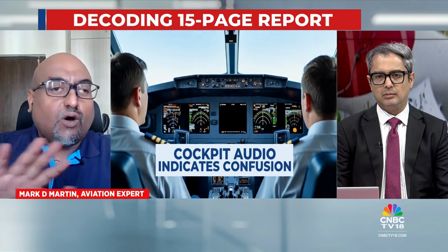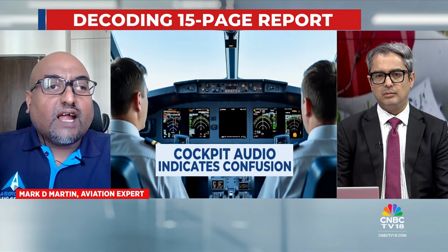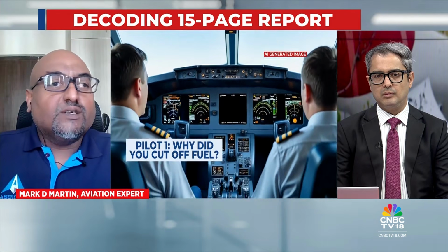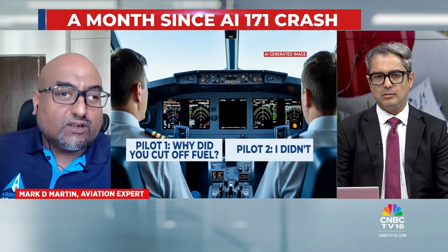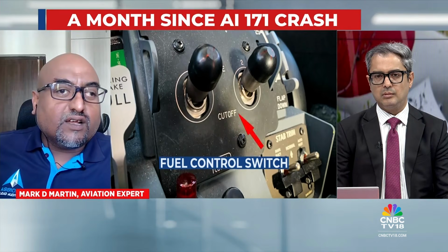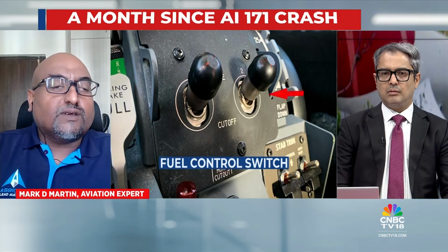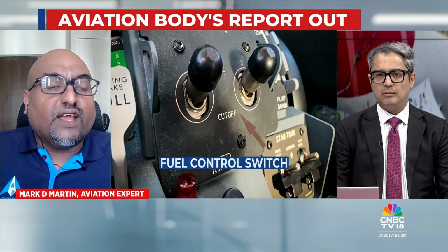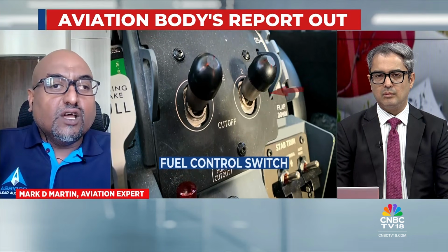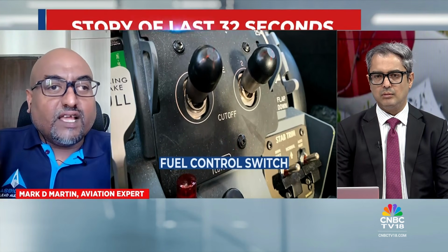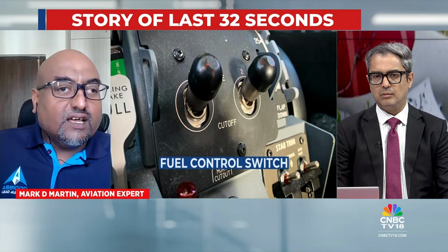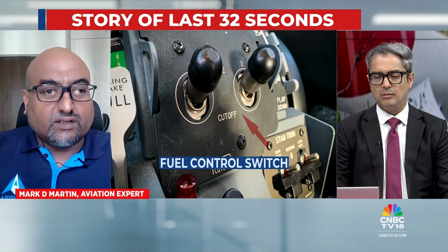The RAT only gets deployed when you have a total failure and an emergency situation. It's an auto logic in the 787, on the 320, on all aircraft. Now, RAT never deploys just because the switches have gone over to cutoff. Switches going over to cutoff does not mean RAT deploys. RAT deploys because it's an auto sensor that everything has failed on board. That's the first thing. So the word is engine failure. And if dual engine failure occurred, then the RAT deploys. That's the first fact on this whole thing.